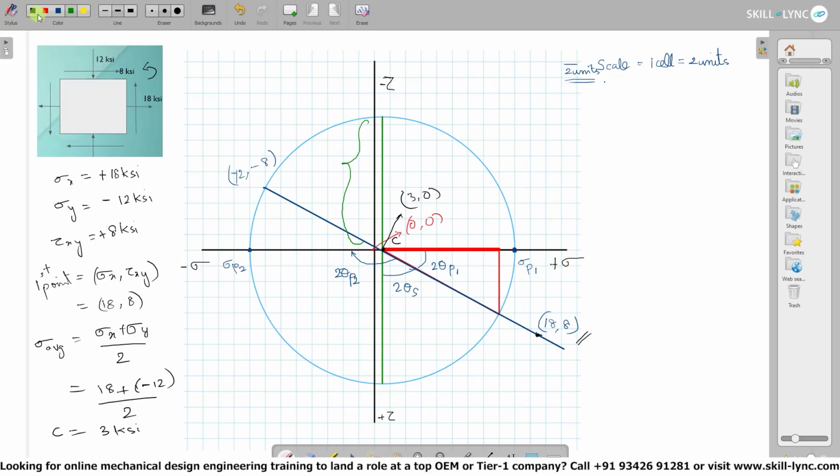So to figure out the radius, first we'll label these points as A and B. We are going to use the Pythagoras theorem. This line, which is the sigma line, is going to be CA. CA equals 2 plus 2, 4, plus 2, 6, plus 2, 8, 10, 12, 14, and then there is one unit here, which is 15. So CA is going to be 15, and AB the same way is going to be 8.